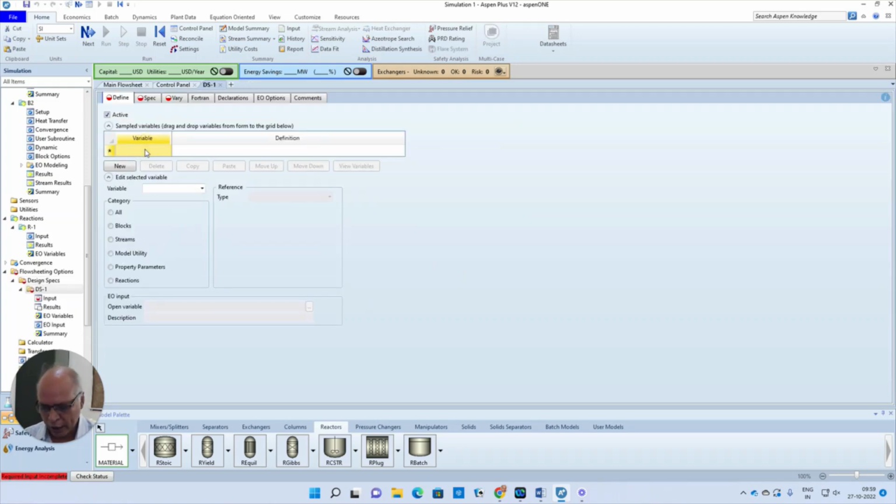Now, I'm dealing with this, of course, we have demonstrated this earlier. Because FNR is 1 and if 90% conversion of ethane has to happen, I will be able to know the molar flow rate of ethane at the exit of the second reactor. So 90% converted, so FA is equal to FNR into 1 minus XA. That means the flow rate of ethane at the exit of the second reactor should only be 0.1.